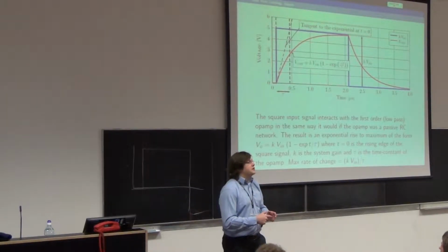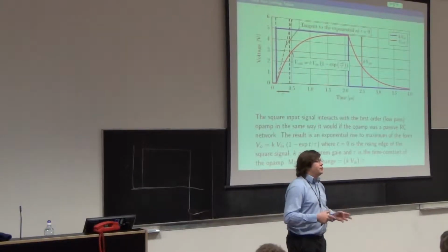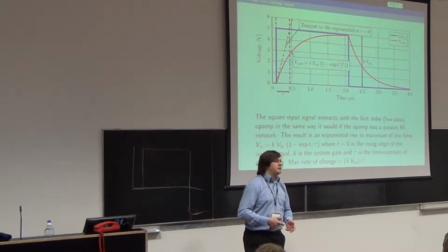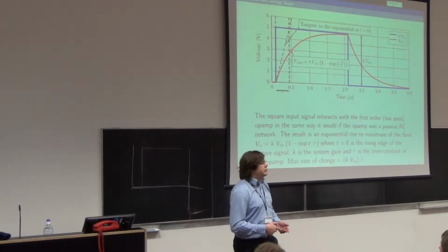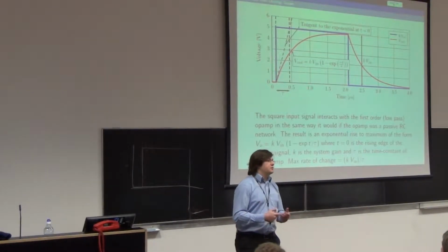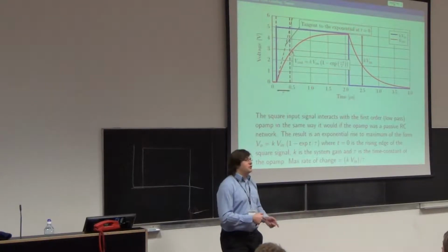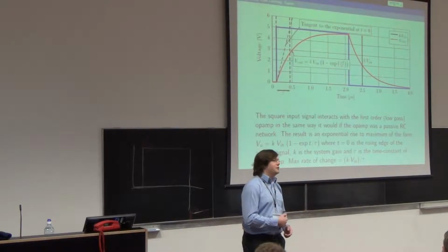Essentially what you're doing is writing out some equations for your op-amp in circuit form and then putting them in a box and connecting things around them and making believe that it's an integrated circuit, which is not really what the manufacturer will supply you if they give you a Spice model. It will be full of transistors and other stuff, and actually if you try to get a nice graph, it will not look like I say it will.